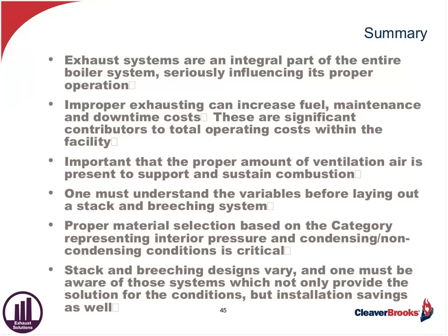Well, let me take a whack at that first, Chuck, if I might. If you've got a number of boilers connected to a common breeching and stack, you're going to have to make sure that it has been designed to be able to handle the maximum. In other words, each one of those is going to have to be sized as though they were all operating at 100% capacity. Otherwise, you're going to get into problems.